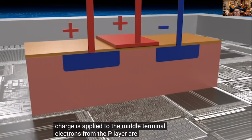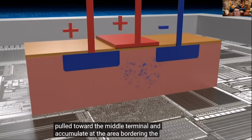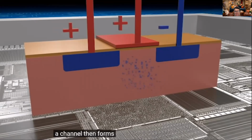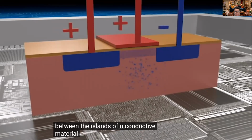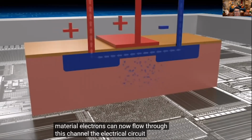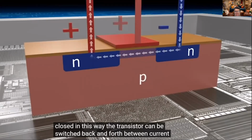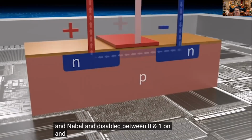Electrons from the p layer are then pulled toward the middle terminal and accumulate at the area bordering the silicon crystal and the insulating gate oxide. A channel then forms underneath the gate between the islands of N-conductive material. Electrons can now flow through this channel. The electrical circuit is closed. In this way, the transistor can be switched back and forth between current enable and disable, between 0 and 1, on and off.